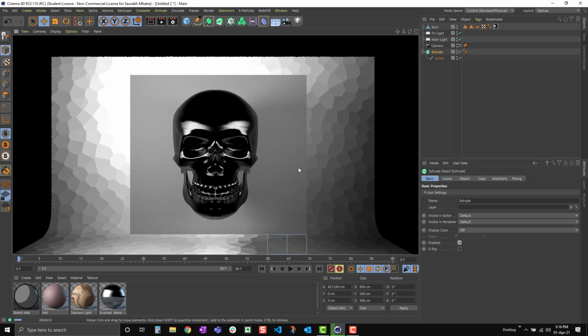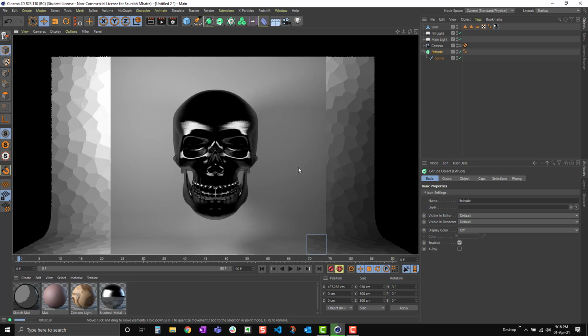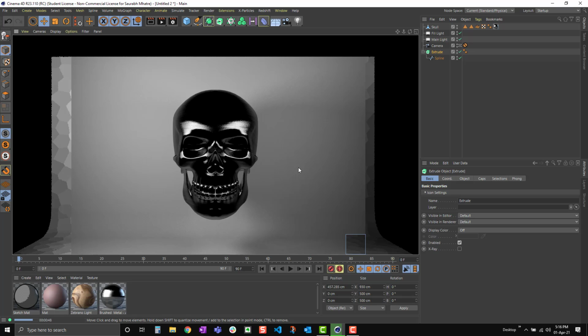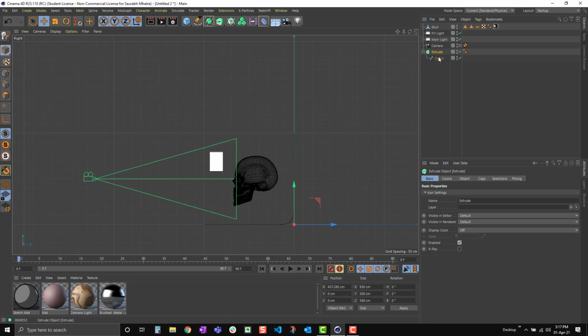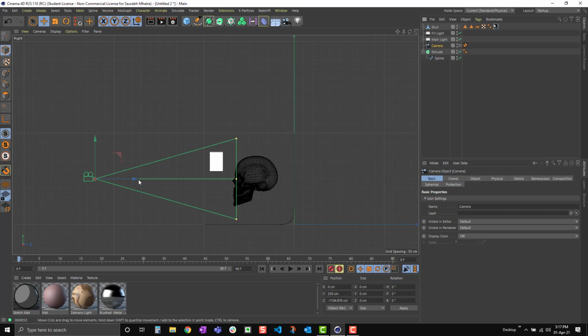And in this physics-based rendering, as mentioned before, we can also play with the focal length of the camera. We can change it so that we get a shallow depth of field, so that your background is more blurred and the objects in front are sharper. All of those are settings you can play with to make your scene more realistic. One way of changing the focus of the camera is selecting the camera.